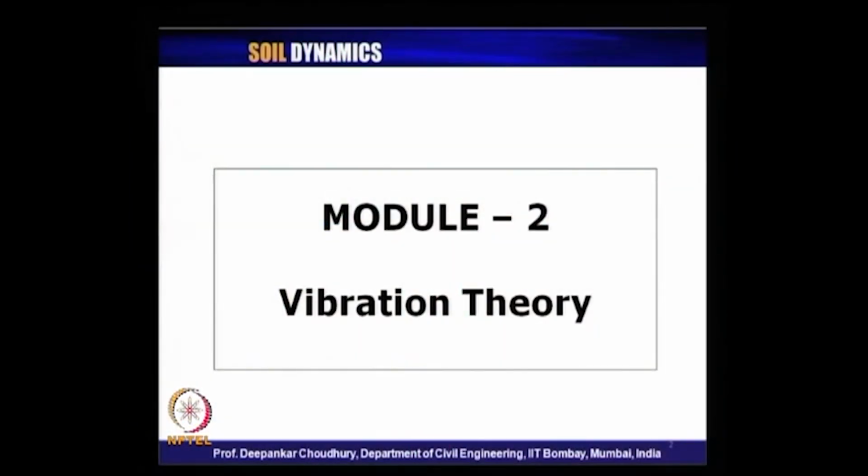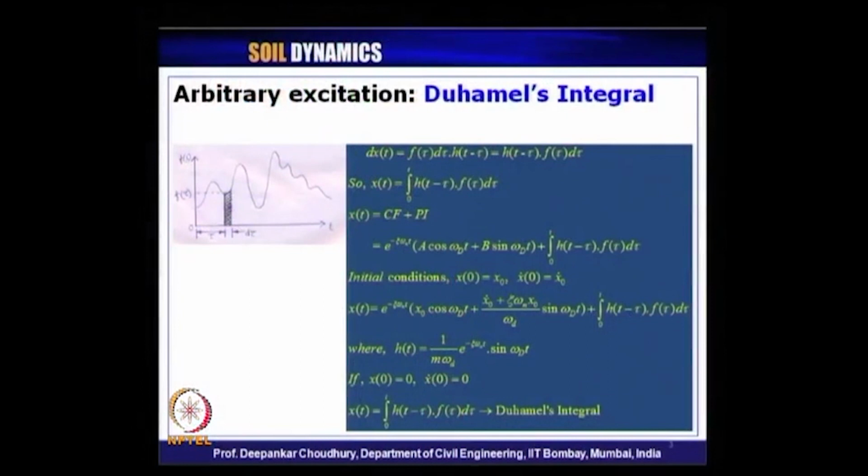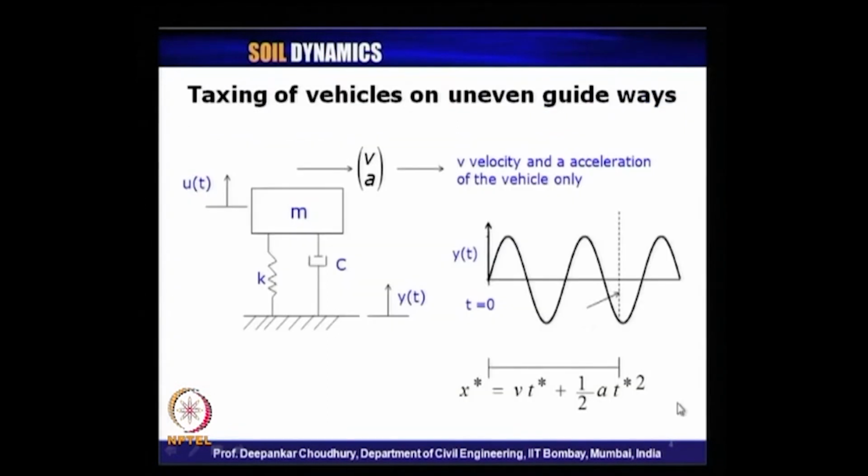Now, we will start today's lecture with module 2 on vibration theory. A quick recap of what we have learned in the previous lecture. We have seen for any arbitrary excitation how we can compute the solution using the concept of Duhamel's integral if it starts from an absolute stationary state. It is similar to the derivation for impact loading, but it is considered in small infinitesimal strips, and then integrating over the entire time for which the excitation is working, we can get the complete response of the system.